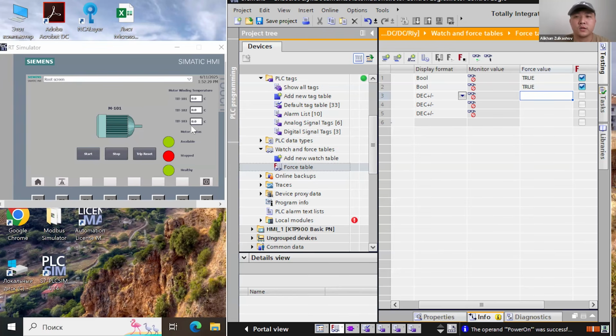There is a term known as safety instrumented system, and it will have multiple safety instrumented functions, each with a measuring device, logic solver, and final control element. These systems responsible for safety will be connected to the safety system. But here, since I have only one PLC, I connected both control and safety to the same controller.